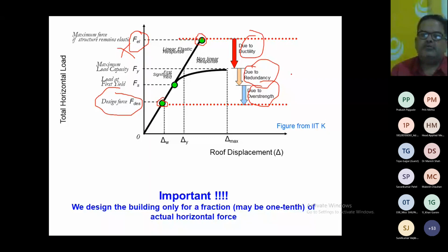So we design for 31 or 32 in the laboratory, which will give at least 25 on site. And if there is good quality control, the concrete may have a strength of 28 or 29, which gives the overstrength. We have so many overstrength factors.